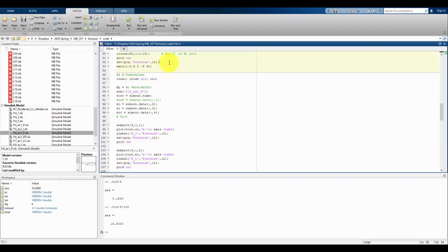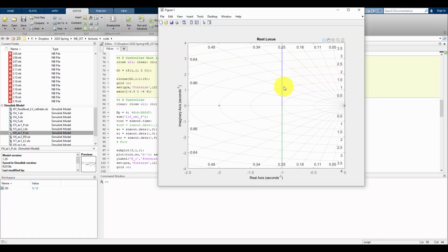And if I go back, I just want to check that again against the root locus, what it predicted. Going back to my root locus and selecting that gain of 4 again, it was saying that with a damping ratio of 0.5, the overshoot is 16.3. Well, we can make that calculation. We know how to calculate max overshoot from the damping ratio. So that should be expected, and we saw that in simulation from the Simulink that we confirmed this.